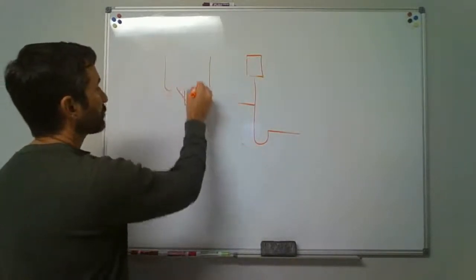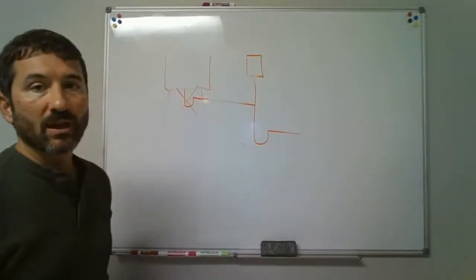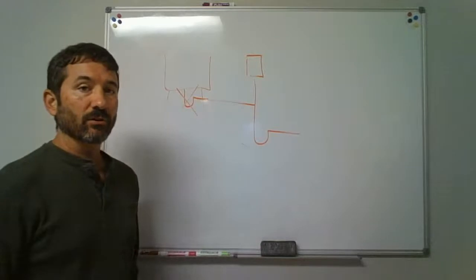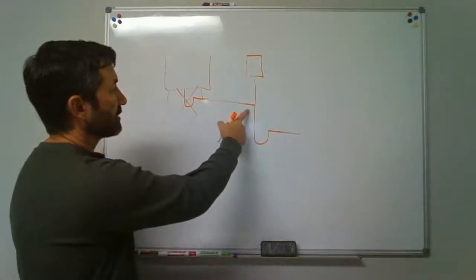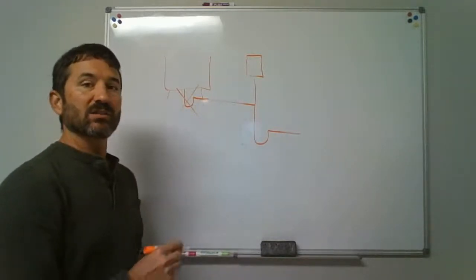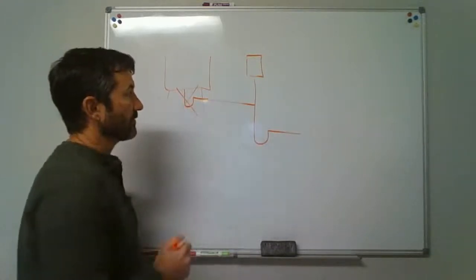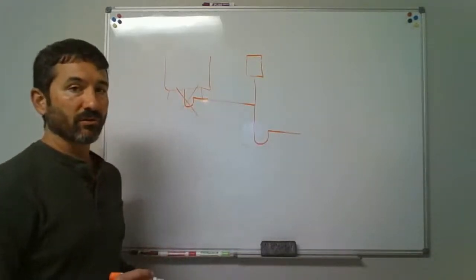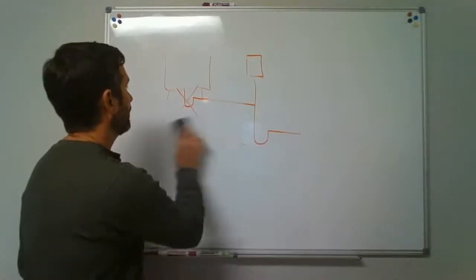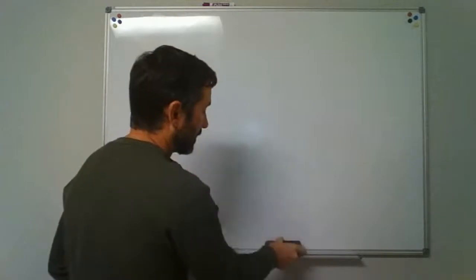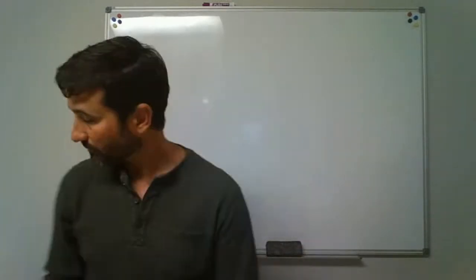So that's a double trap. We should not have a trap on that fixture. Now, it also has a maximum distance of 30 inches on this. Remember in chapter 3, it says you could tie into there as long as the center from the center of this connection over into the standpipe is not more than 30 inches on that. So we're not allowed to double trap it.